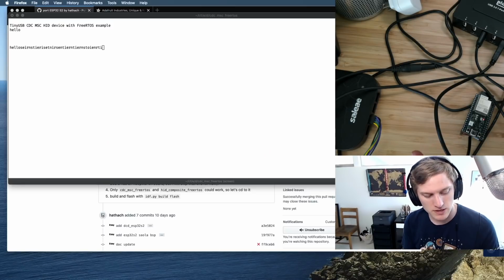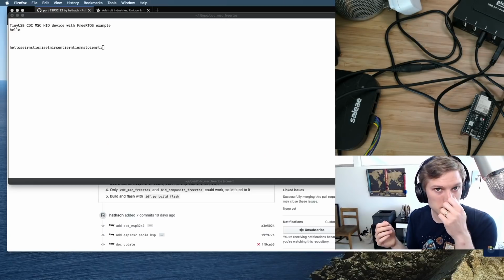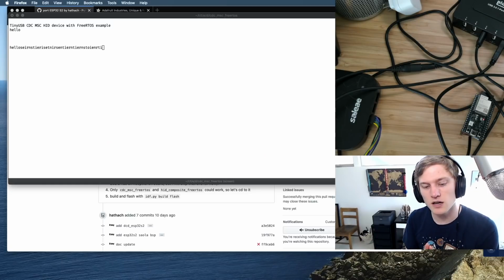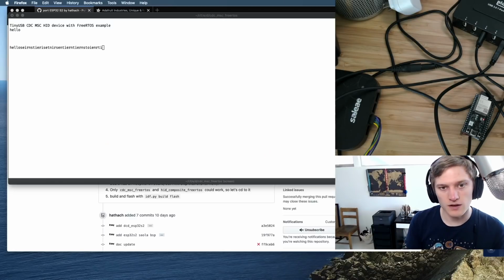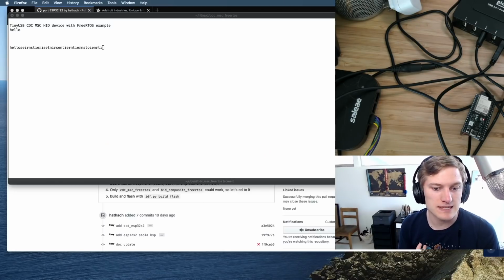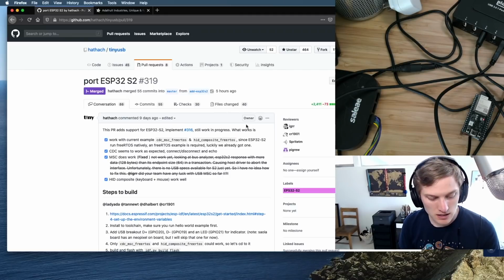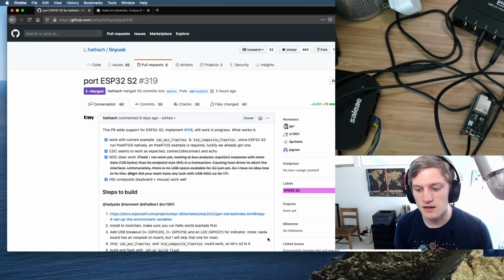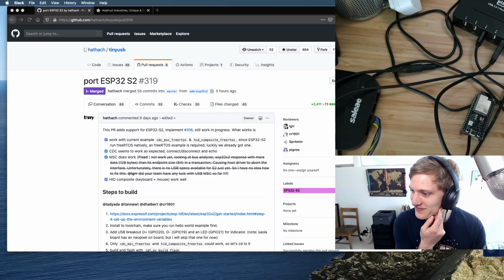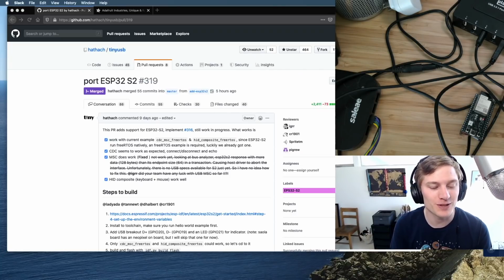What we have is the ESP32-S2, which is a brand new chip from Espressif that is somewhere between their ESP32 and their ESP8266. It's single core. Actually, we could talk about that. We could pull up the data sheet. How fun is that? TinyUSB is an open source USB stack that TAC works on along with some volunteers. TAC is paid by Adafruit to work on it along with other stuff for Adafruit. CircuitPython uses TinyUSB at its core to do all of the USB stuff that it does. That is critical to the way that CircuitPython works by showing the drive and automatically refreshing when you save a file.